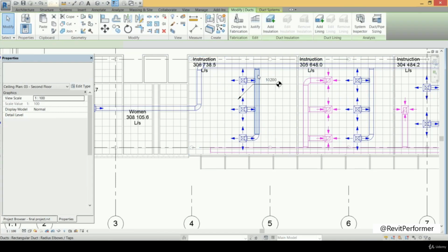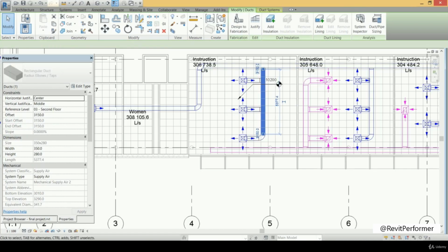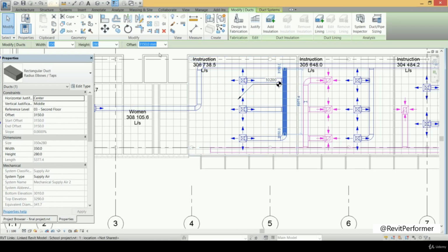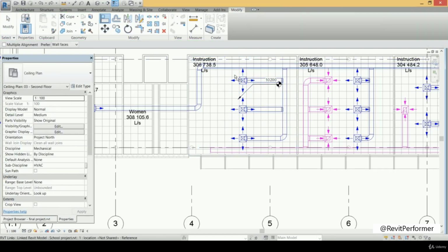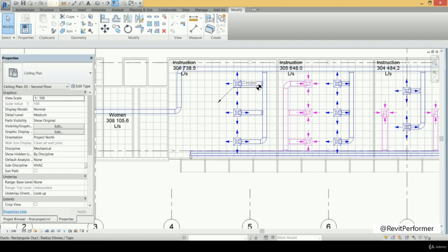So we can drag the duct right here by pressing the right arrow on the keyboard, and then we align those 3 diffusers with that line, for example. So we go to the align tab and then align those 3 diffusers with that line. We press on that line and that edge of the diffuser, and the same line and that edge, and also the same line and that edge of the diffuser. Very good.